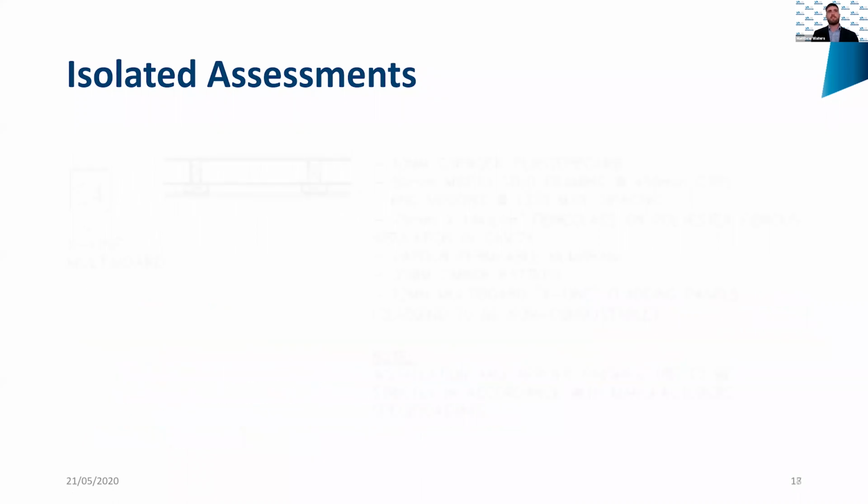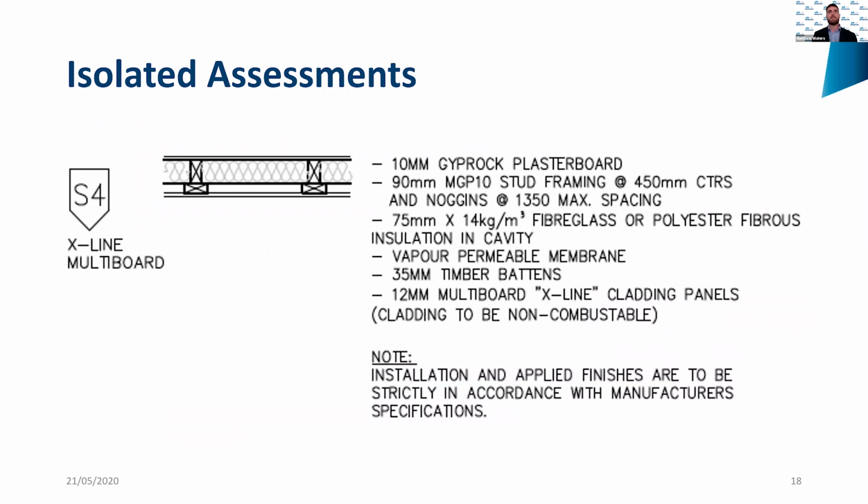And then when we went to the specific wall that the openings were in, the plans show the wall as wall type S4, which we've shown on the screen. Now this wall required a fire resistance level of 90 minutes, so 90, 90, 90, under the DTS of Spec C1.1. And obviously C3.2 only applies where a wall is required to have an FRL. So the performance solution considered the protection of openings and then assumes DTS compliance for fire resistance levels.